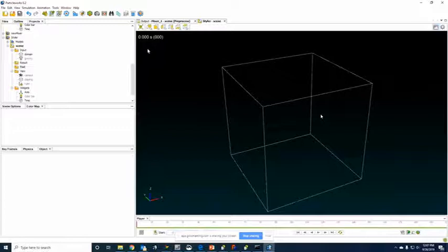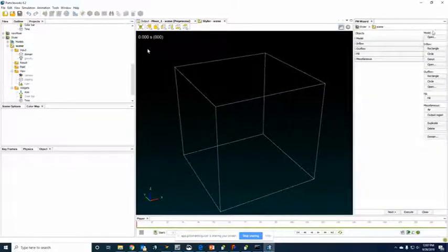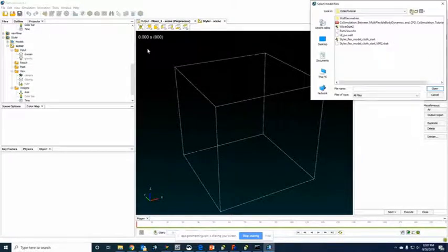So I open the scene, and now I'm ready to import the geometry that I just created in RecurDyn into Particleworks. And the way that I would do that, I like to use the wizard in Particleworks. It gives you a step-by-step process of how to do things. And the first thing that you'll want to do is open the model open. That's how you import geometry in Particleworks.